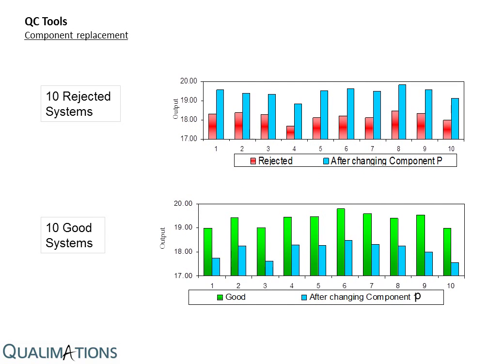Consider component search on an electrical part with several subcomponents, by swapping the good subcomponents with bad parts and also by replacing bad ones with good subcomponents. Their results should vary based on the output. This should also be repeated on many samples. In this case 10 samples are studied of both the good and the bad part.